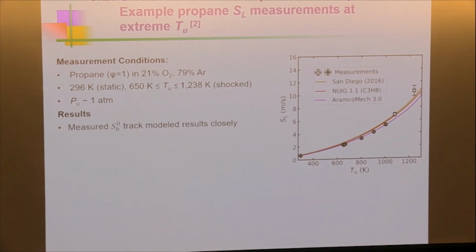What you're after is called the laminar flame speed. It's the speed at which a laminar flame would move if it has no stretch. So you have to watch this spherical thing grow. You get the speed in the burned gases, and then you have to transform that to the unburned gases, and you have to remove the effect of stretch. So there are some steps involved to go from the experiment to this, and then you measure it versus T, and then you begin to compare it with different mechanisms. And the fact is, there's never been a flame experiment above about 800 degrees Kelvin before.